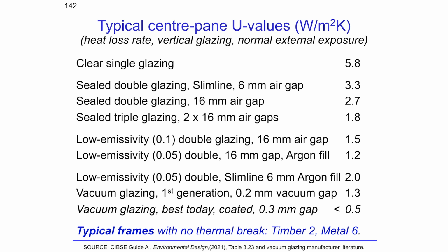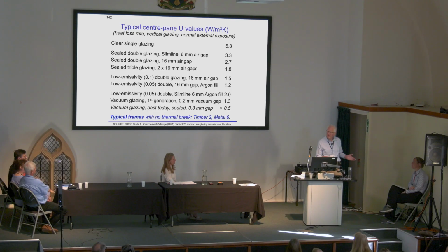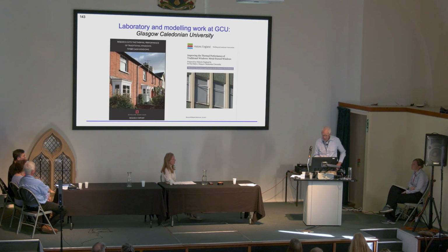And if we go to slimline, not quite so good. Now, the problem with argon fill in slimline, argon fill in anything, is the argon fill gradually comes out through the perimeter seals. So in about 10 to 20 years, a lot of it's gone. So a lot of what it's sold on is no longer there. You know, the slimmer the gap, the more likely it is to get out earlier. So there's an issue always with modern products that they're great, but will they last?